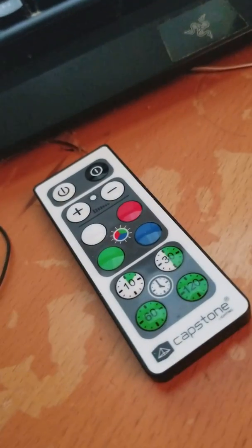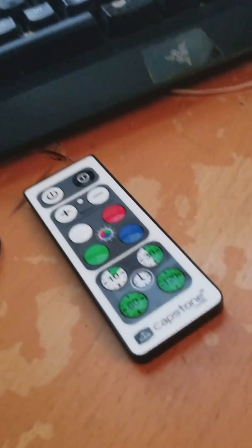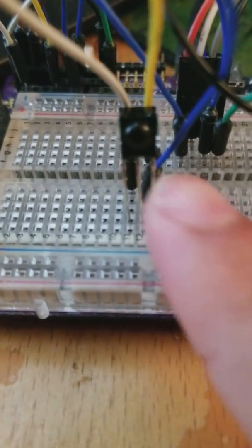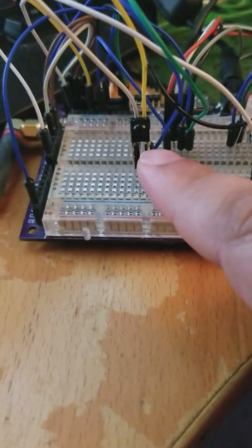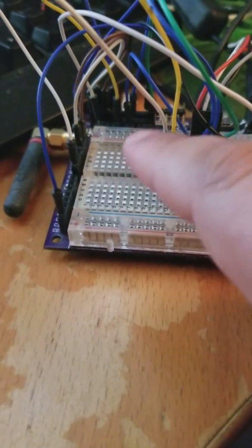So what I wanted to do was decode this one. This one takes a little IR pulse. You can see it, infrared, and that infrared signal is picked up by one of these. It's an infrared receiver. It looks for that 38 kilohertz frequency as sending data. So the little device there is going to decode the data, and I have it fed